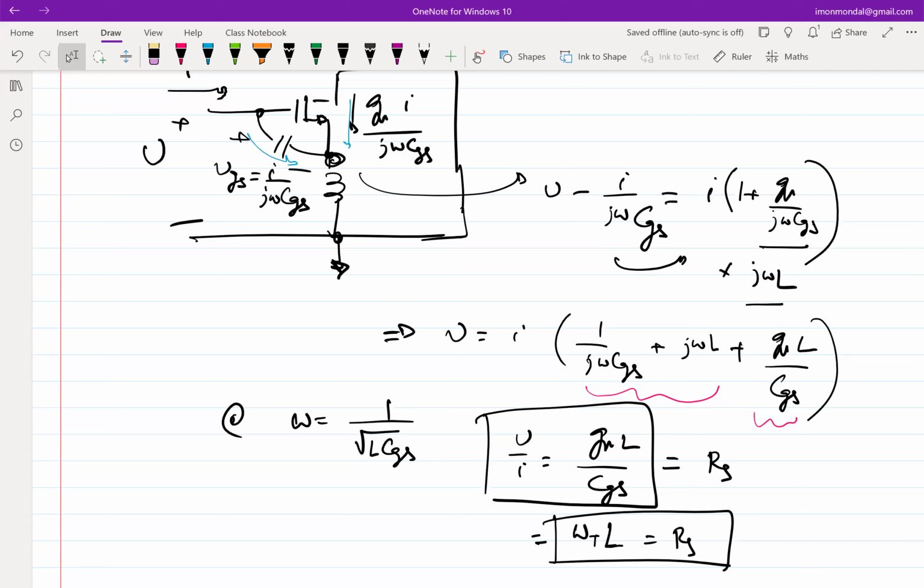But L is a design variable, right? But you might think that in this case, if I change L, the center frequency is changing. I am saying that CGS I will not be able to change independently, but that's not true because you can change CGS provided you are okay with changing GM also. Basically, you have to keep omega t constant. If omega t remains constant, if you have one circuit and you copy and paste the same circuit again, your omega t doesn't change, but the input impedance doubles. If it's in parallel, it halves, or CGS doubles. So you can basically scale CGS up and down.